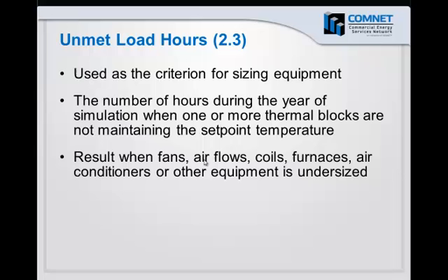It represents the number of hours during the year when one or more thermal blocks are not maintaining set point temperature, or one or more systems are not making capacity. And this can result when equipment is undersized: fans, coils, furnaces, air conditioners, and so forth.